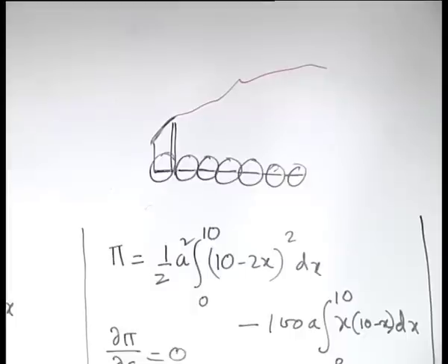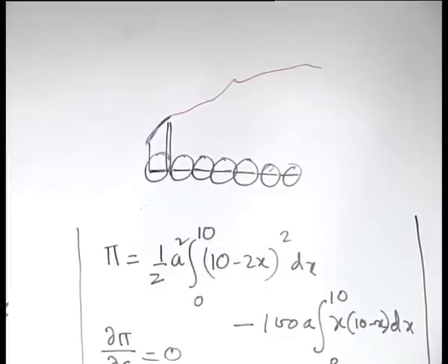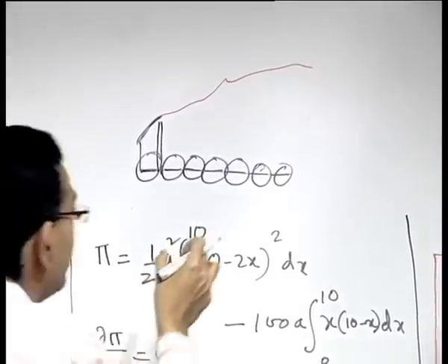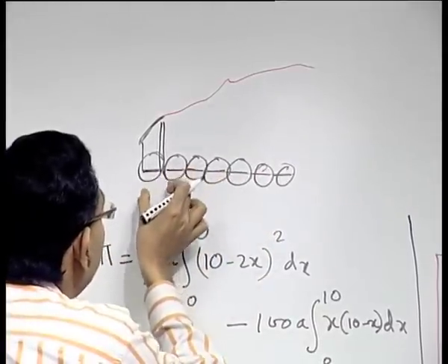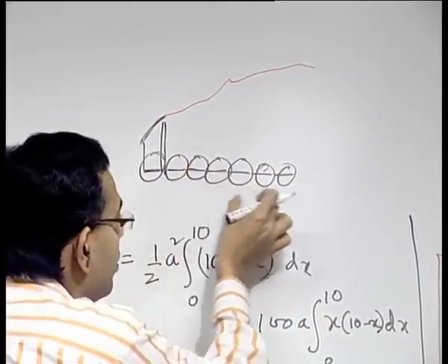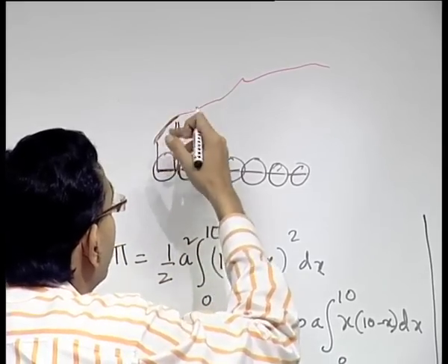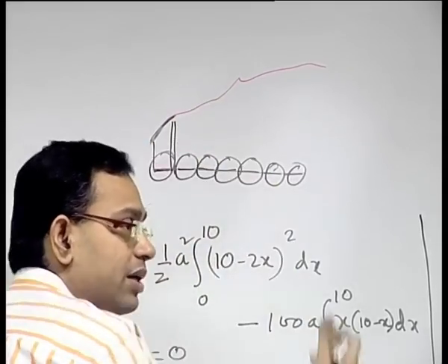So, you are reducing the requirement of the order of your polynomial, but the cost you pay is that you are dividing your domain into a discrete number of subdomains, and for each subdomain you go for a lower order polynomial to approximate your solution.